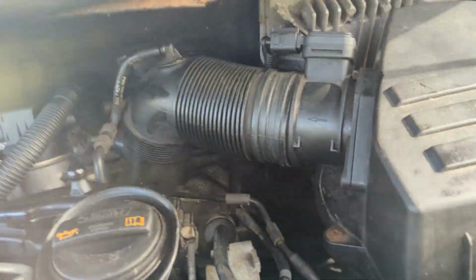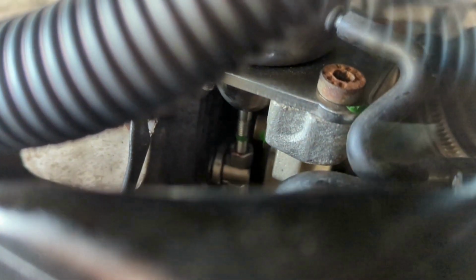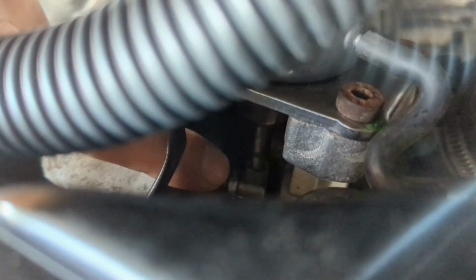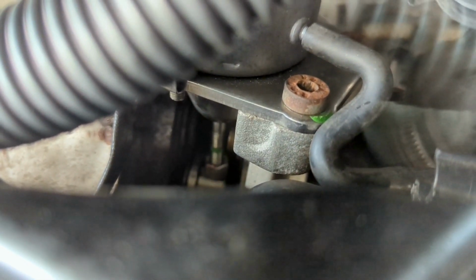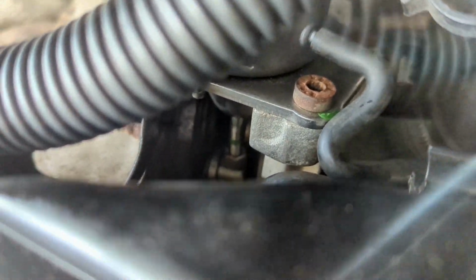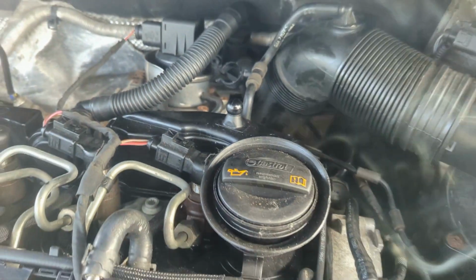Right, I've just pulled over because we're down on power, coil lights flashing, but I don't know if you can see, when I fitted this, I had this top nut wound up to that green sort of security pin marking. It's obviously wound its way down, vibrations and stuff from engine. We've got a circuit low fault on this now. I'm going to just wind that back up, nip everything down, go on a good test drive.